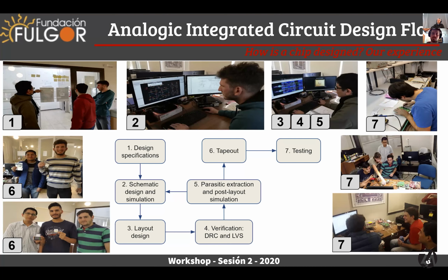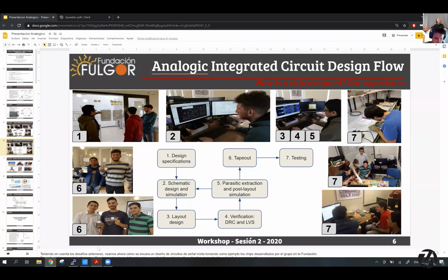Well, I have to respect the transistor size that I set on the schematic design. So when I run the LVS verification, they will match. If not, I have two different transistor sizes, and that's an error. The layout does not reflect the schematic. Okay, so in your schematic, you might say this transistor needs to be a higher current one, so it needs a bigger, for example, diffusion zone or whatever. Exactly. For example, let me show you.